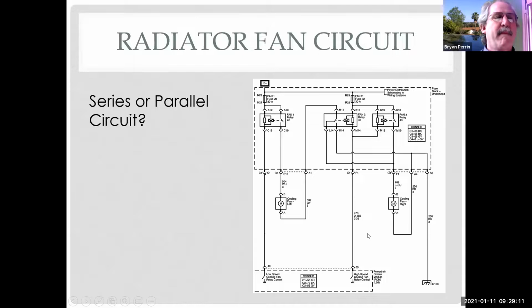Okay. And if they're only using 6 volts instead of 12, does that mean they're going to spin slower? Yes, they should. So that's your low speed fan on your radiator. And then they switch the two series circuits into two separate parallel circuits when they want high speed fan, and then they can control them individually. I see, okay, that makes sense now. I got lost there for a minute, but now I know what you're talking about.